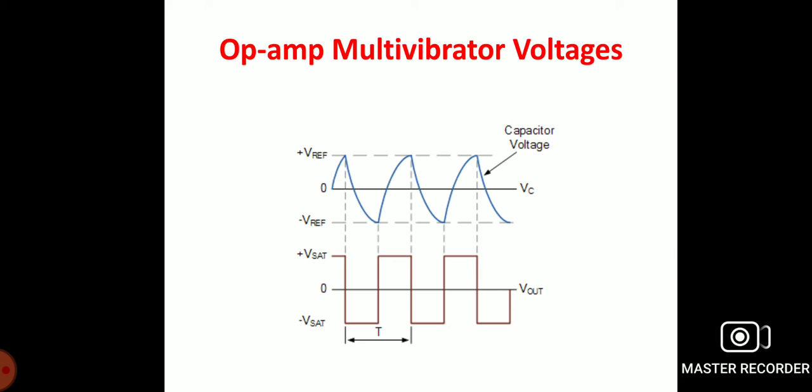The period of the output waveform is determined by the RC time constant of the two timing components and the feedback ratio established by the R1 and R2 voltage divider network, which sets the reference voltage level. If the positive and negative values of amplifier saturation voltage have the same magnitude, then T1 is equal to T2 and the expression is given. The period of oscillation becomes: